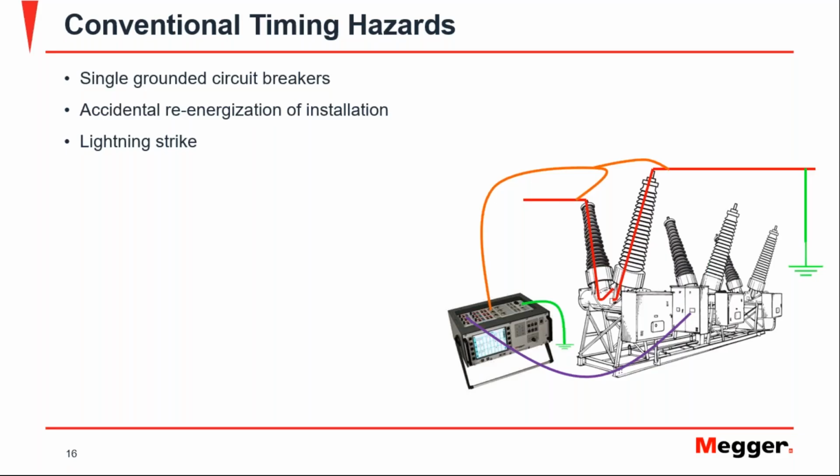So I mentioned that for the test, you have to unground one of the sides of the breaker, because the way the test is performed is with a continuity measurement. You're applying voltage here and determining the moment that this contact closes, with the resistance threshold.